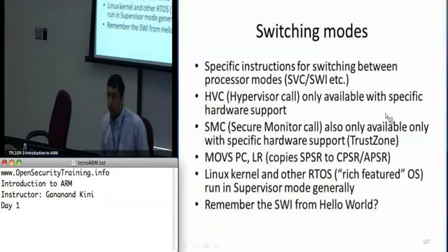So when we want to return from our mode back to user mode or back to supervisor mode, or whatever mode we're coming from, it's going to be saved in the SPSR. And when we copy the link register back into PC, we can't restore the SPSR at the same time back into CPSR, because if you write the SPSR back into CPSR, the mode's going to change, and your next instruction is not going to be executed. It actually causes the mode to change, and it's going to go back to your interrupt vector table.